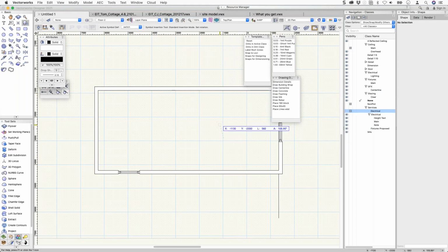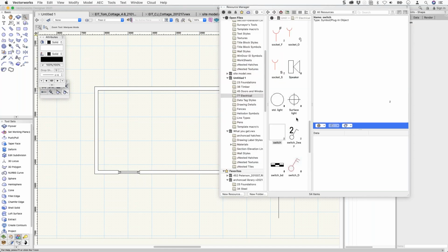So that means that I don't have to think about what class I'm putting those on because the class is taking care of that. I don't have to worry about whether it's breaking into the wall or inserting in a wall, so I've taken care of that as well. And if you really want to go nuts, you can also edit the three-dimensional hole option to make a hole in some places and not in others. It's really quite cool. Symbols are really powerful. And the final one I wanted to really get to think about,